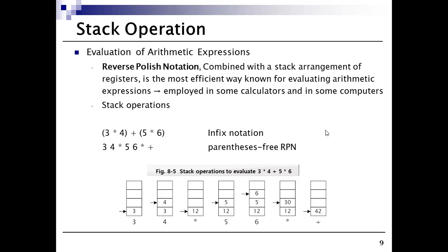And the second way of organizing the CPU is general register organization, GPR based organization, where we are using multiple registers. Okay, like from R1 to R7 as an example that we have seen. Multiple registers are used for holding the operands, and the operation is performed between them. Okay. And the third way of organizing the CPU is stack based organization.